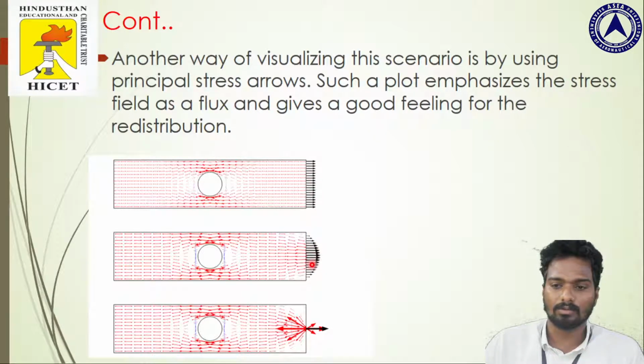As you come down, the redistribution of forces here doesn't produce any change in the three cases, whereas here, due to the redistribution, there is a change in the stress concentration at points very close to the area or surface where the force is being applied.